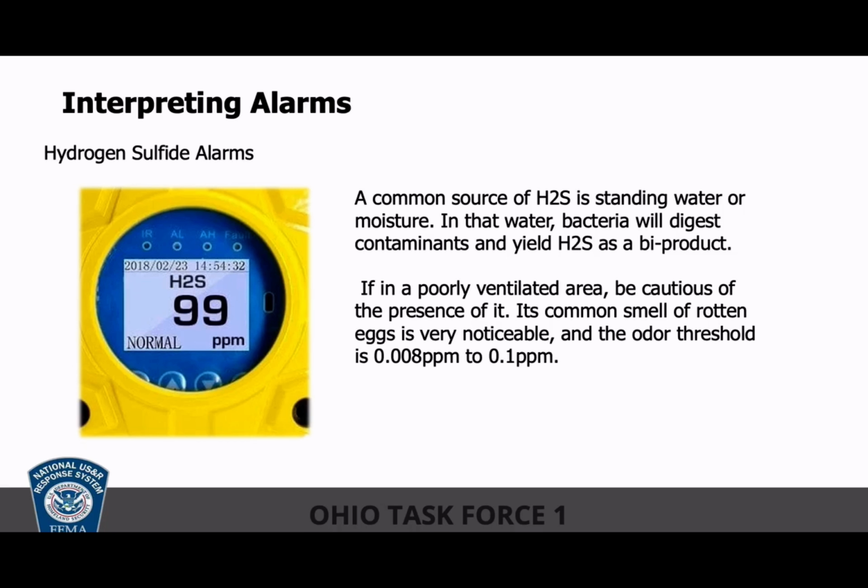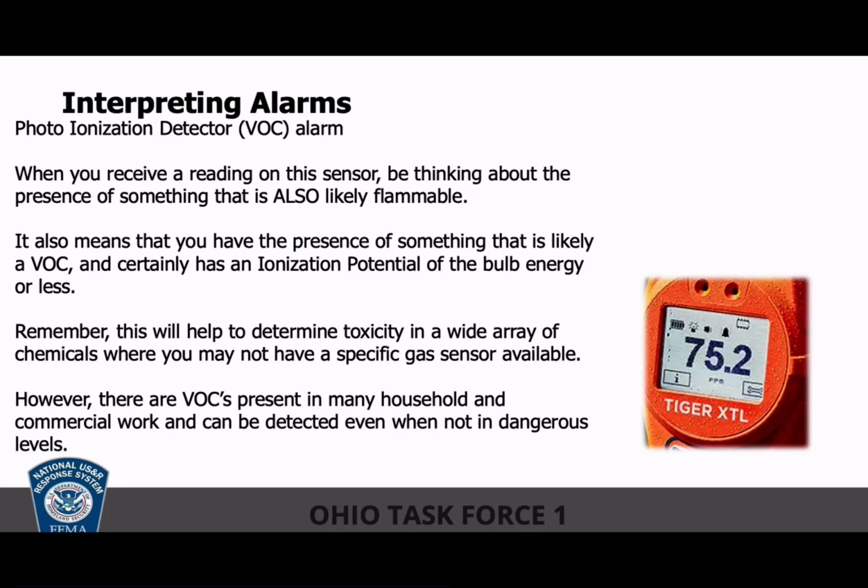However, H2S has an odor threshold of 0.008 ppm to 0.1 ppm, so most people can smell it well below where it becomes a problem. We said its IDLH is 100 parts per million, so we can smell it 1,000 times before it becomes a problem for us. If you can't smell it, or if you're in SCBA on supplied air so the odor threshold doesn't apply to you, just be wary of the fact that we need to meter and monitor for that.